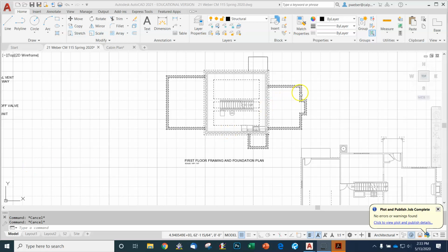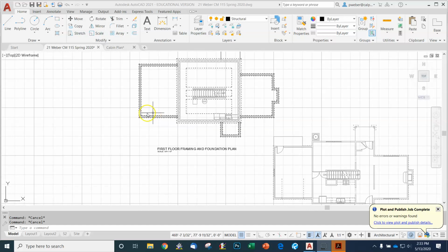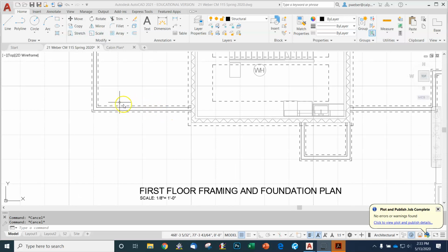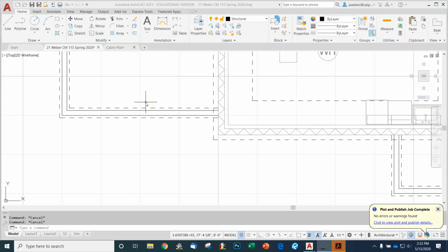The next task we'll use is going to be to dimension the plan. We've got a few other things I want to tweak in here before we dimension the concrete masonry units, the CMU units for the basement, and for the concrete stem walls. So let's see, I want to hatch some of this stem wall. But remember, we're driving in the middle of this stem wall with a car. We have a 9'4" opening.